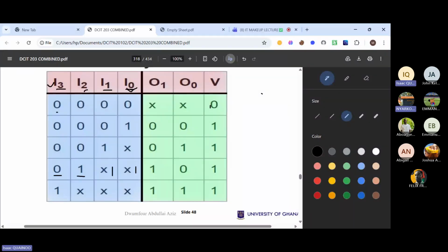Please, should I continue? What is the binary output? All right. So what is going to be the binary output? We have D3 is 0, D2 is 1, D1 is 1, D0 is 1. Now the question is, which one has the highest priority? We all know that it is this one, right? Can you see that?